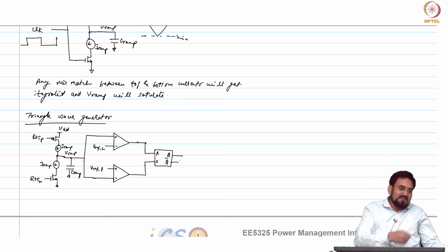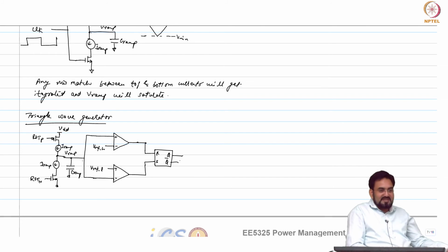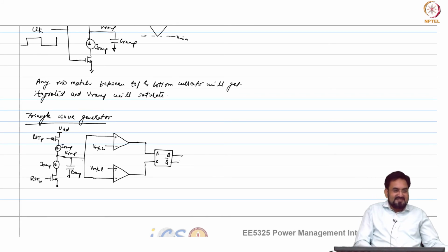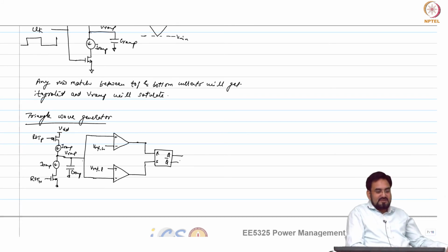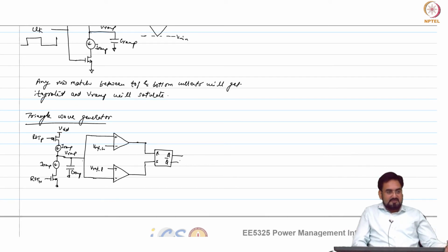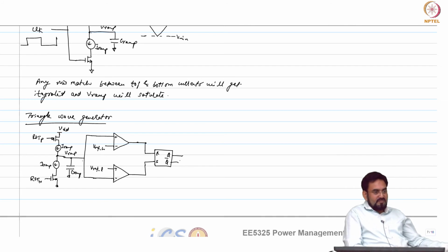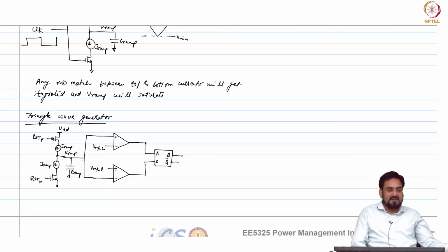But it's a P and N MOS, ultimately they should be driven from the same signal. You can put an inverter and separate the signals, that's fine. If your switches are of the same type, then it has to be driven with a complementary.